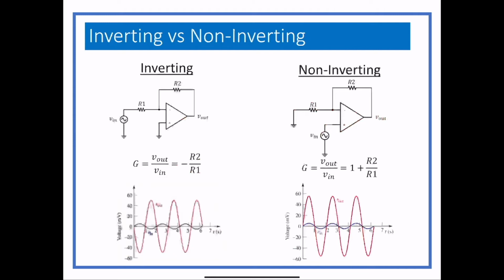Op-amp amplifiers can amplify DC, which is different from most amplifiers. Most amplifiers can't process a DC signal. Op-amps can. You can actually send a DC signal in and get the gain times the output. The only limit on an op-amp amplifier is the DC inputs you put in, so you can't get out more than usually plus 15 or minus 15 in the output, or the space between.